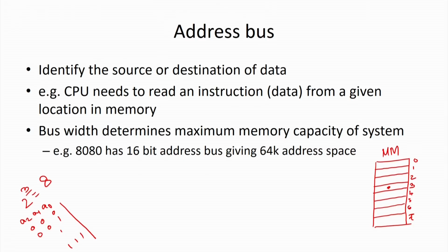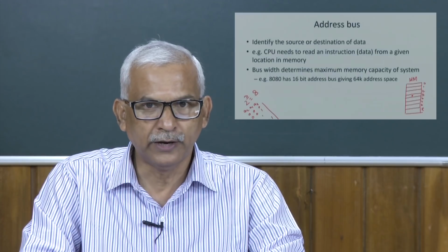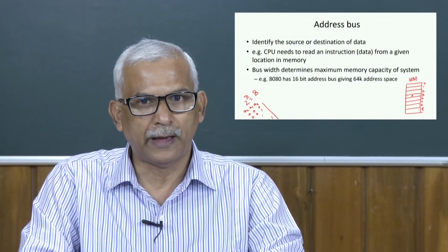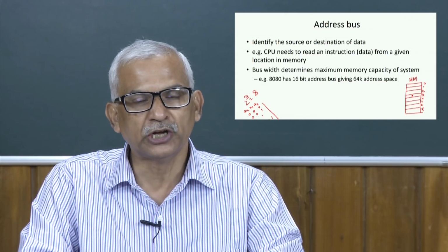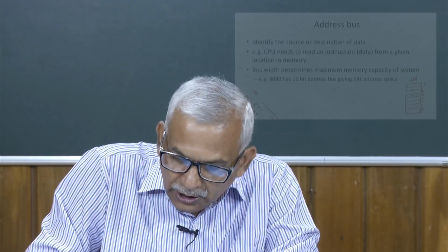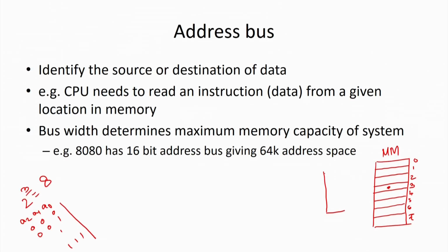We have already talked about a decoder. We know that we have a decoder where there are some n input lines, and the maximum number of output lines will be 2 to the power n. Depending on the input combination, one of the output lines is high. So, in that particular case, what can we do? We can use a 3 by 8 decoder. We have 3 input lines, say A0, A1, A2, and these output lines will be connected to those particular memory locations.